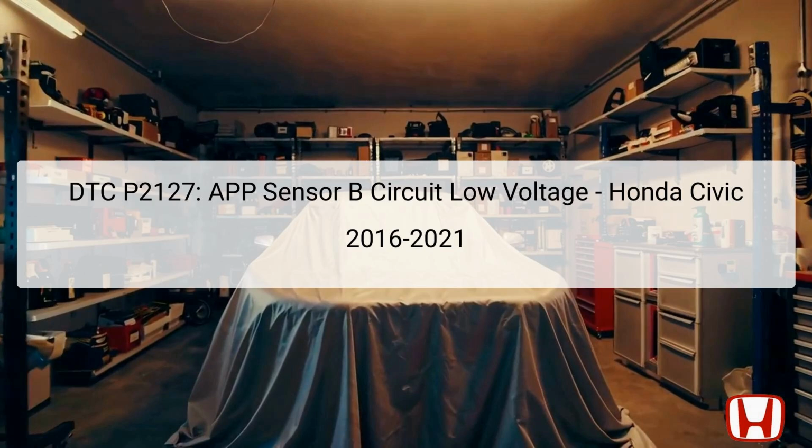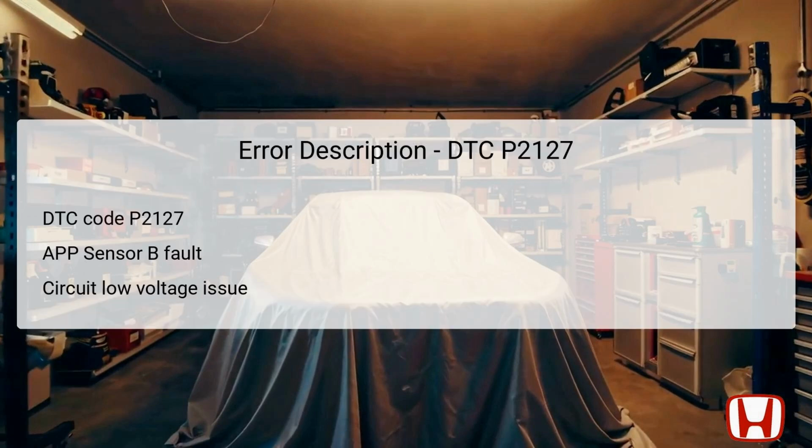this fault promptly. The error description for DTC P2127 highlights a problem with APP sensor B, which directly corresponds to the throttle position sensor E. The APP sensor sends voltage signals to the powertrain control module, PCM, allowing it to determine the throttle position. A low voltage condition means that the sensor is not providing adequate data to the PCM, which can disrupt the vehicle's performance.